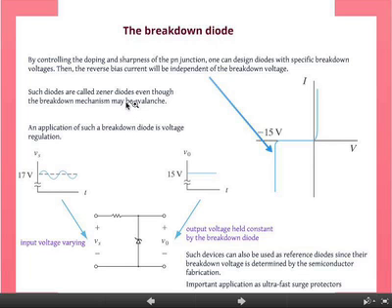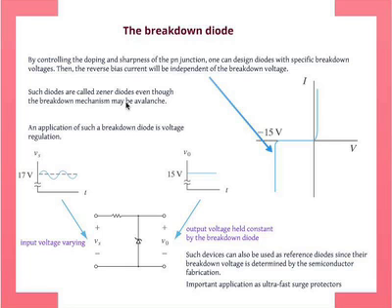Okay. So one interesting point here is that these diodes, if you buy them, they're all called Zener diodes, even though most likely the mechanism is avalanche breakdown. Okay. Typically, it's avalanche breakdown because it's very hard to get the N plus P plus, very, very high doping on both sides to Zener. But you can buy them as well. But they're all called Zener diodes, so just don't be confused if you actually see any of this.